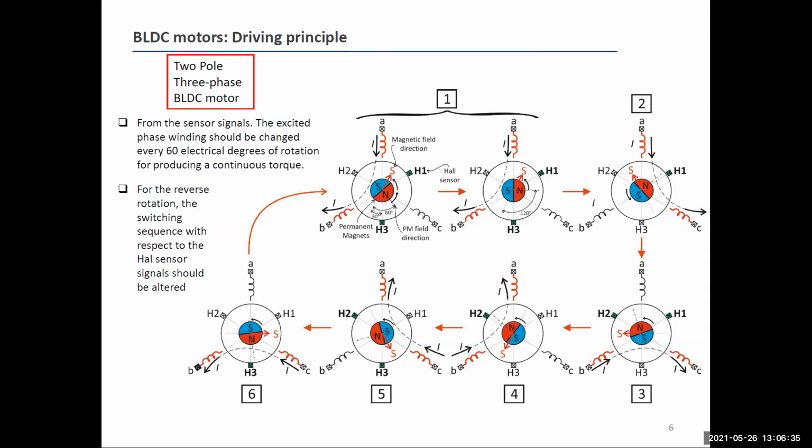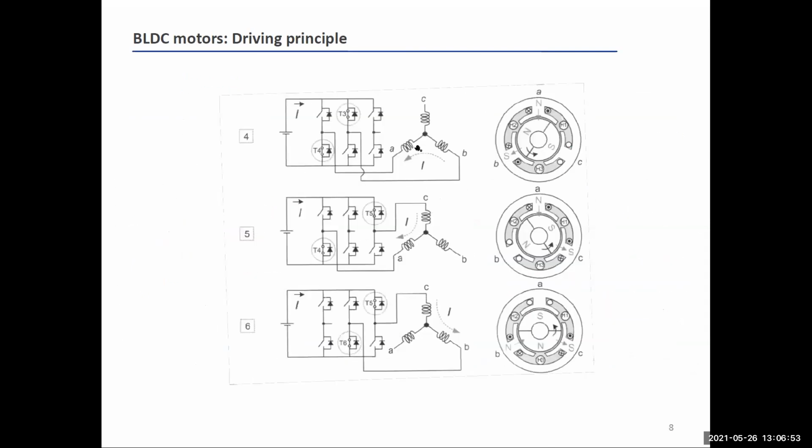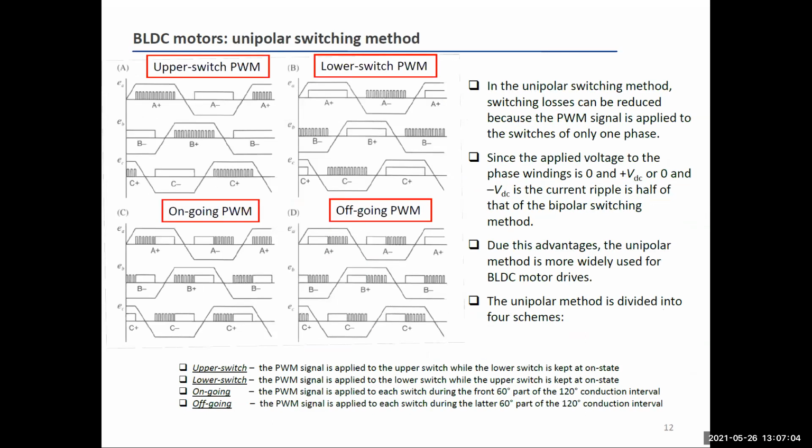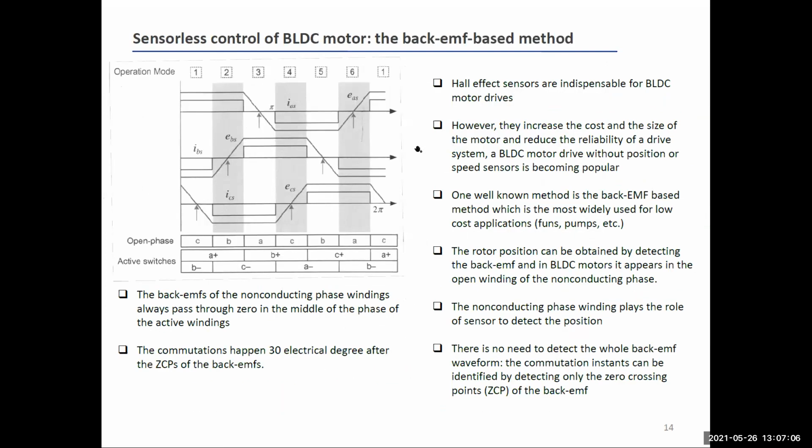And so certain research has been made in recent years to make the brushless DC motor operate without using Hall effect sensors. This is called the sensorless control of brushless DC motor. How can you control, how can you choose which of the three legs I have to energize and which one I have to leave open, by not using the sensors? So look at this slide here.